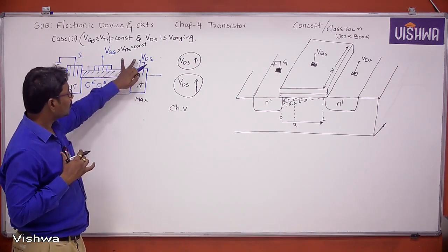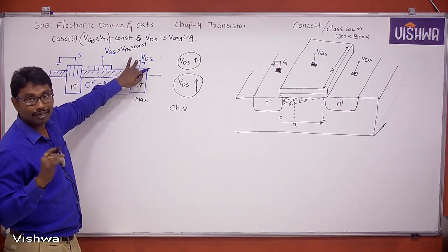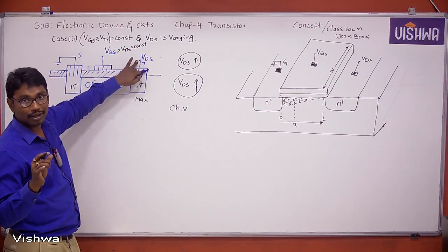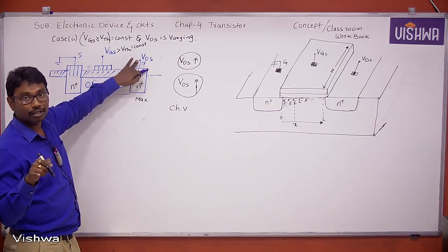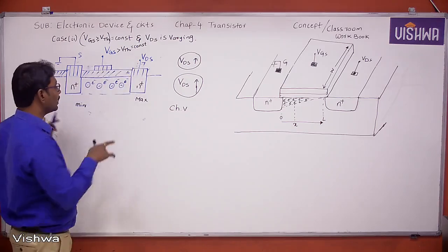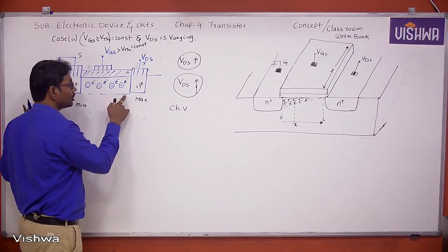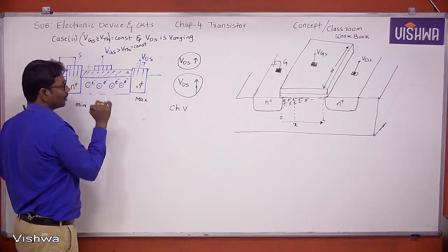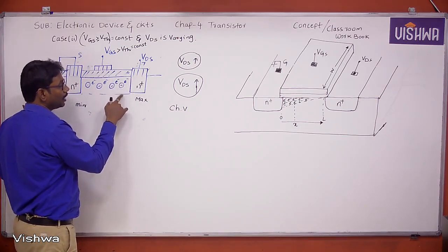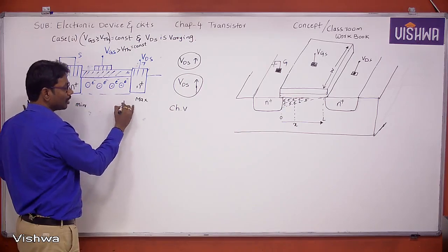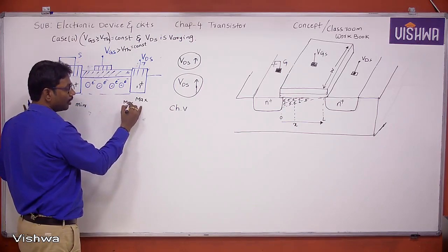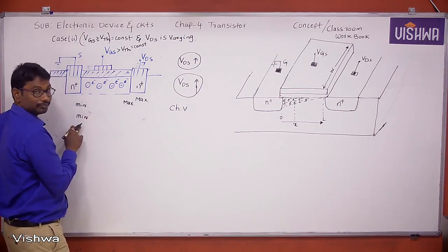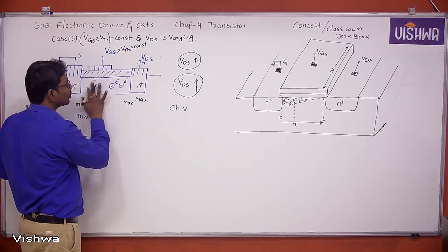This channel voltage is also used to make the channel junction reverse biased, due to which the depletion region increases at the channel junction. You know that the increased depletion region is maximum at the drain end and minimum at the source end. So how does it look?